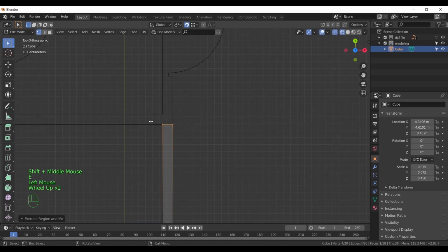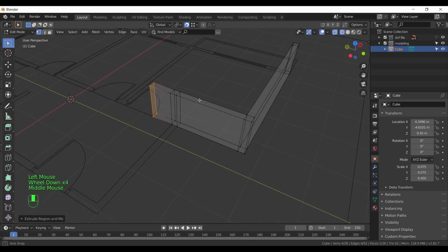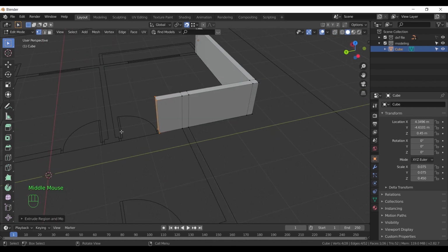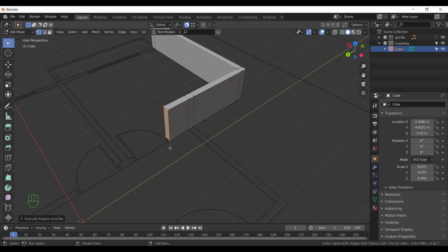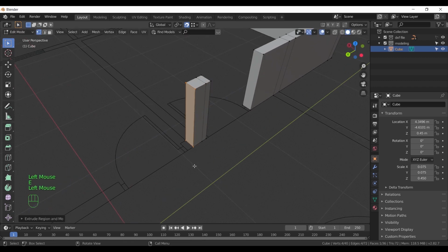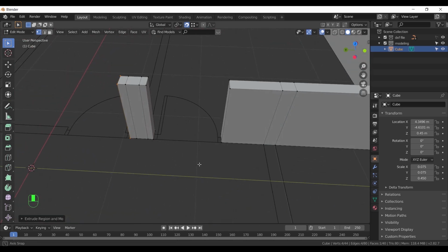Make sure to extrude the walls in each corner so that we can close the wall correctly. Once you reach a door, to skip this area, we will copy those 4 vertices and snap them to the opposite corner, then we can continue with extrusion. The process is repeated in each wall, so I will comment when needed.